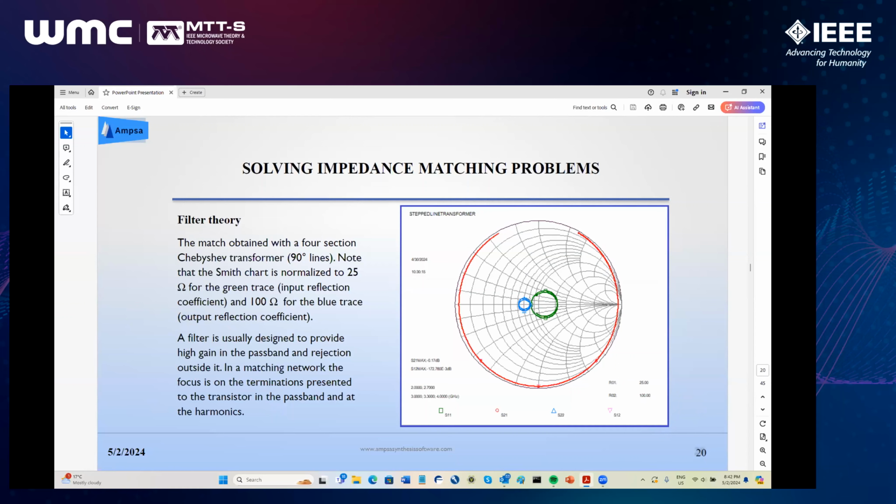So you can see the match would be there in the middle, but it actually makes a little circle. So it's doing the pass band not so wonderfully, and it also makes some other big circle in the rejection band. So it's doing two things: it's controlling the pass band and it's controlling the rejection band. So its purpose is slightly different than what we want. We actually would like those to be dots, which they are not.